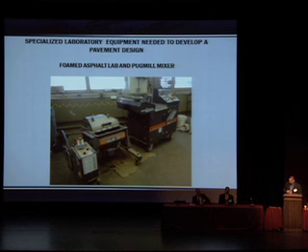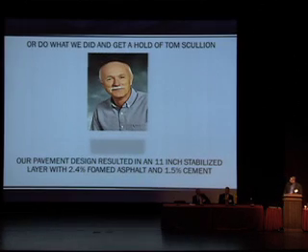So you can invest in a high dollar piece of equipment, or you can do what we did and contact this guy. Again, working through the maintenance division, we were able to tap into Tom Scullion, and he prepared our pavement design. He came up with a mixed design of 11 inches with a 2.4% foamed asphalt and a 1.5% cement.